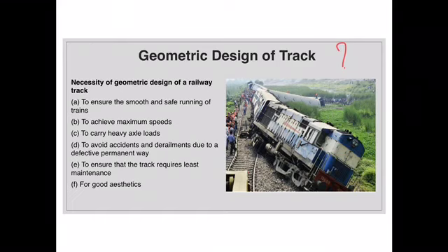The cost of construction may increase very much, improper gradients may lead to accidents, and construction of a new track requires a huge amount of investment. Because of improper geometrics, it may be very difficult to upgrade the existing condition, the budget requirements would be very high, and the cost of realigning any network will be very high.